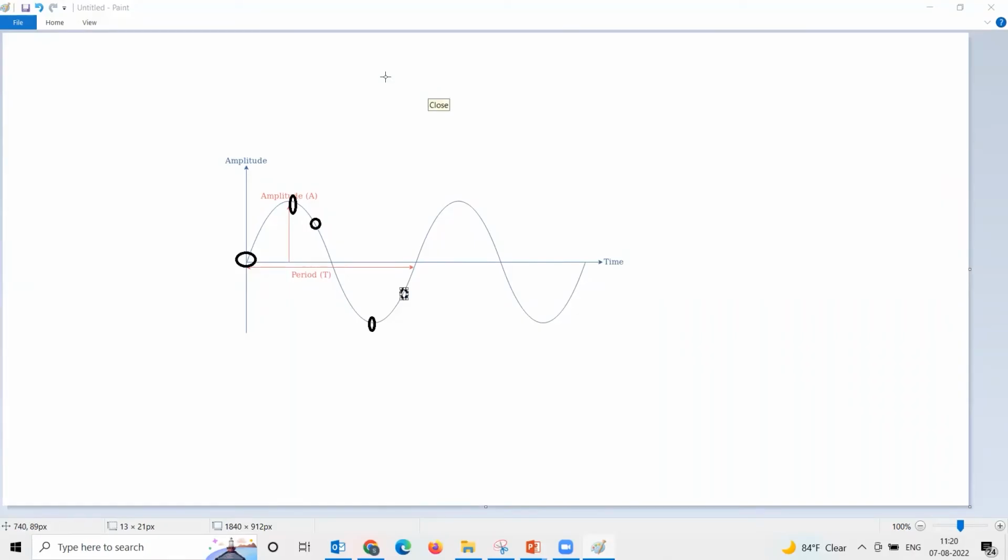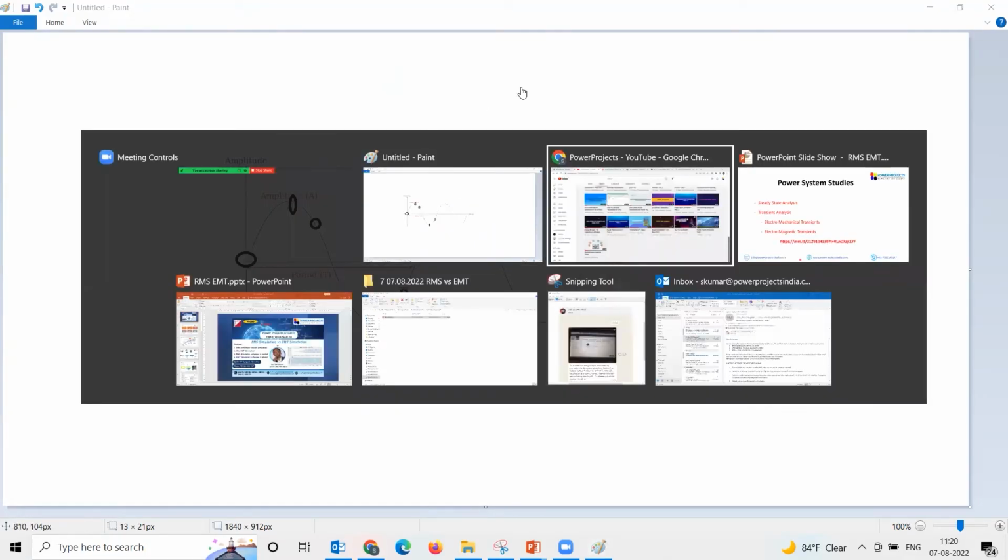Nothing else, right? So there will always be a confusion or clarification, like whether simulation will match with the reality. Simulation will match when you are performing a load flow, and if you are finding out the voltage drop when this much current flows, that definitely matches with the simulation as well as the practical, provided you have done the right modeling of the transmission line, right? But when there is a fault, the fault current in ETAP and the actual scenario will never ever match, because we do not know the instant at which the fault has occurred. Right. With that, let's go back to our system.